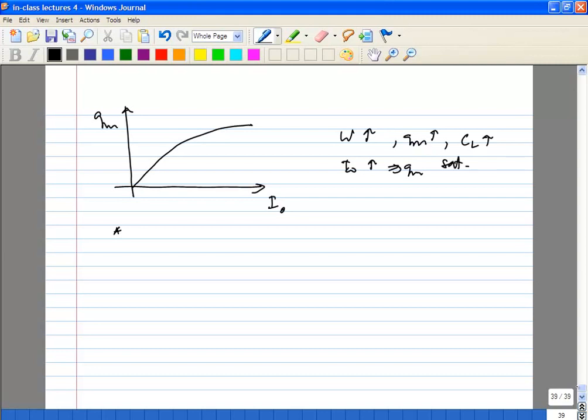The other thing you can do is cascade a number of amplifiers. We'll look at it next class. That is another way to do it, which is you basically cascade, and that lets you get out of this trade-off for a single amplifier. But at the end of the day, each amplifier is going to have its own delay. So if you're cascading n amps, you're going to have n times the delay of each amp. So at the end of the day, what you're actually doing is,